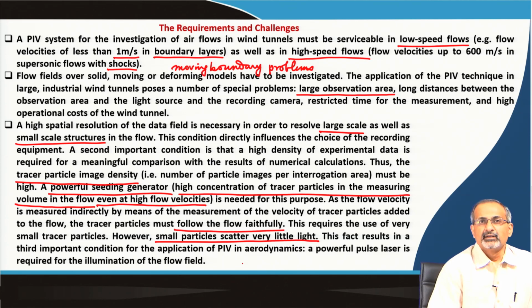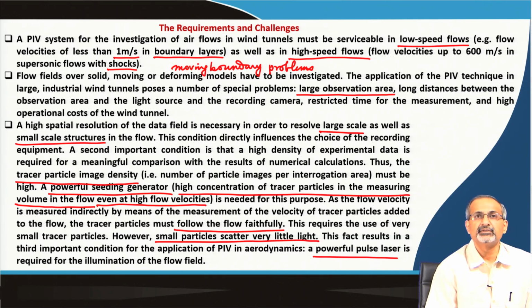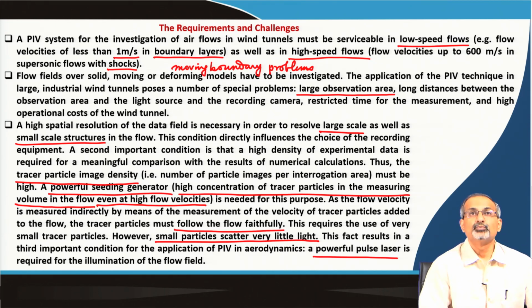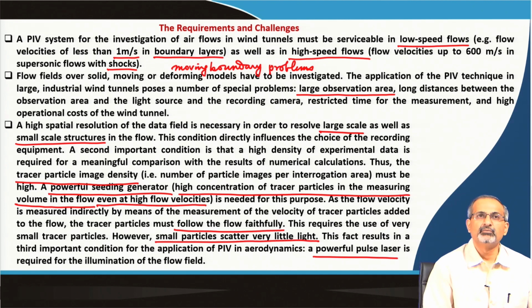So this essentially results in a third important condition for the application of PIV, that is a powerful pulsed laser which would illuminate the flow field even if it is laden with very small sized particles. So put together, there are a lot of requirements and challenges which are specific to the problem, but the more challenging the flow problem, the more stringent are the requirements, the more the challenges.